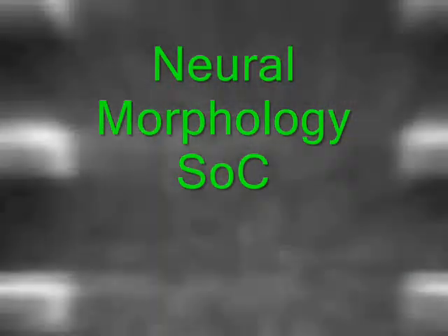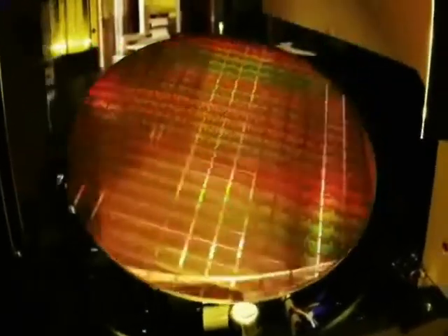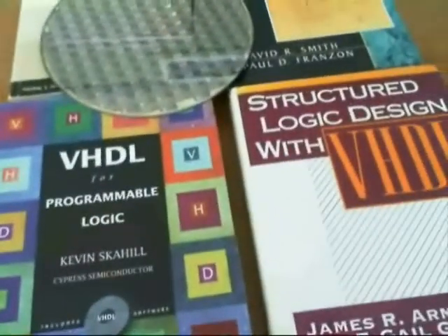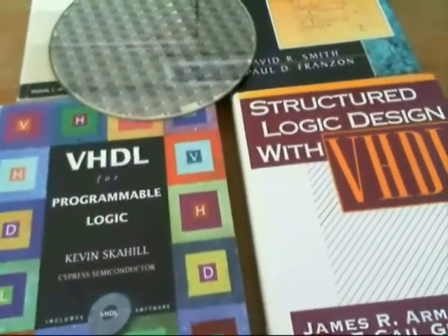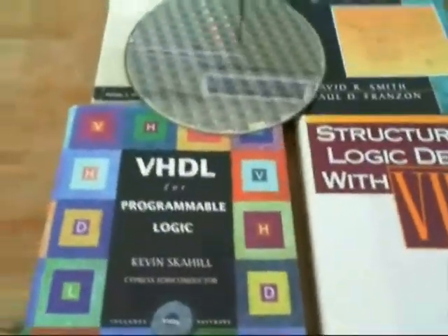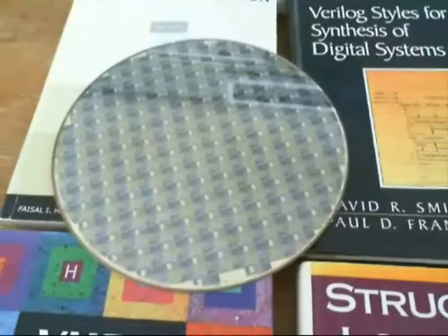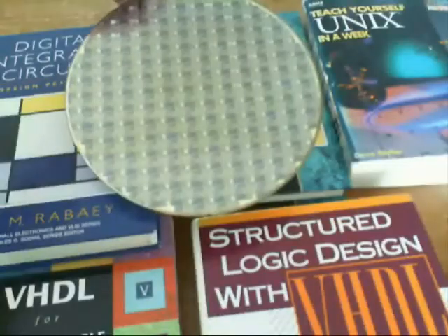One particular nuisance is the two-bar effect, where a pair of identical bar-shaped features do not focus identically. One feature is essentially in the shadow of the other. The two features generally have different CDs, which change through focus, and these features also shift position through focus.